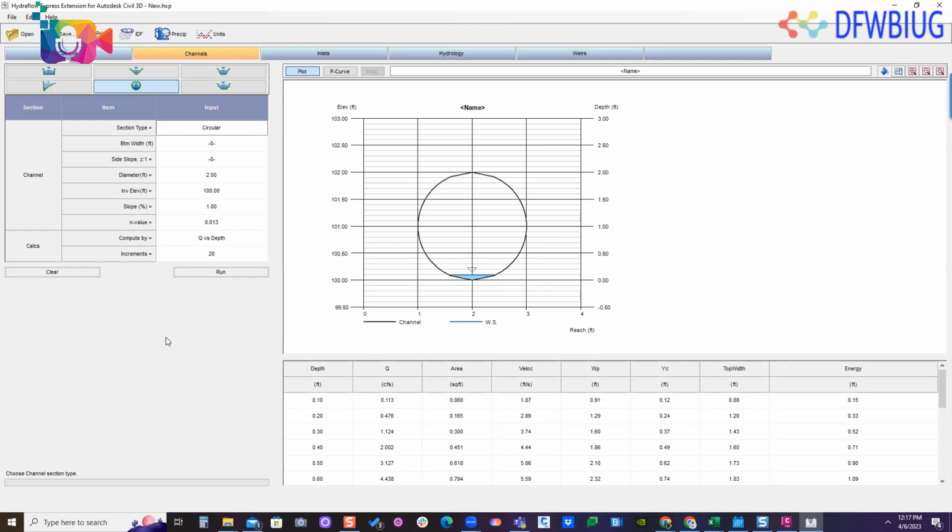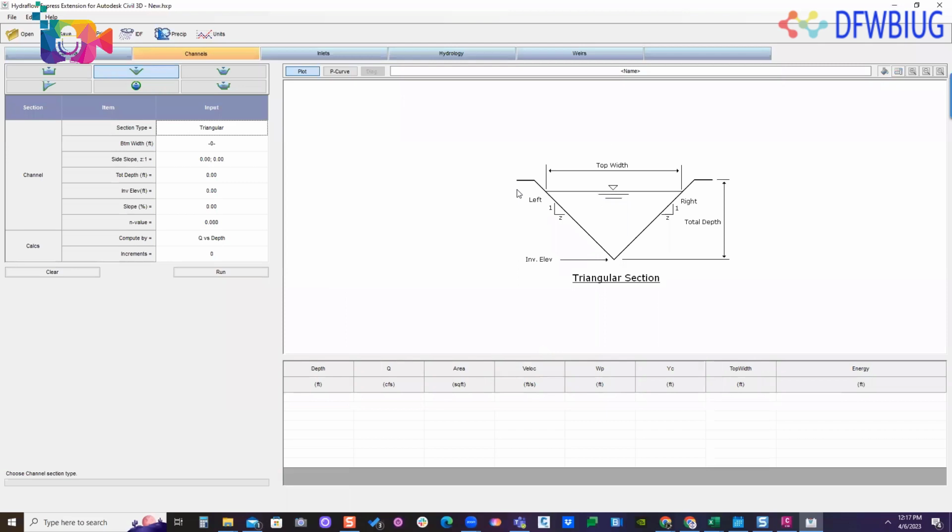Now, if I'm doing a swale, and you've got a swale in the back of the yard or a big drain swale, this is where I can come in and do a drain swale and say, okay, I've got 4-to-1 on both sides. Maybe the depth is going to be 4 foot. I'm always just using 100.